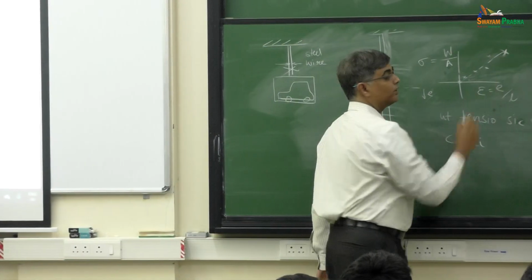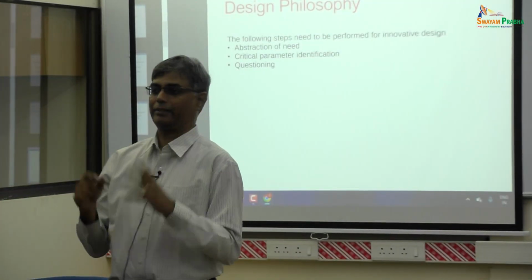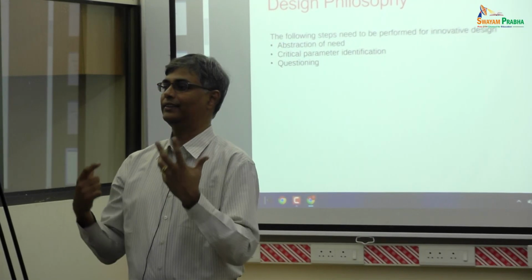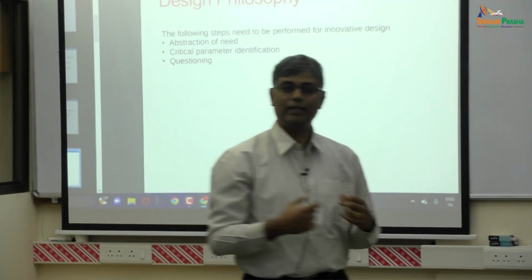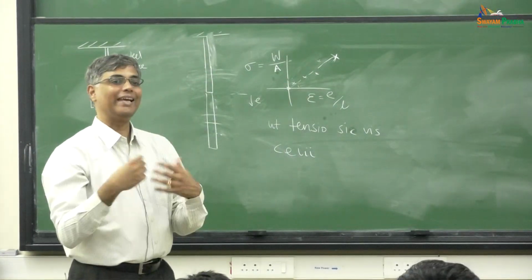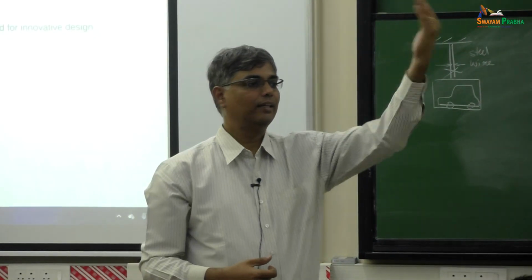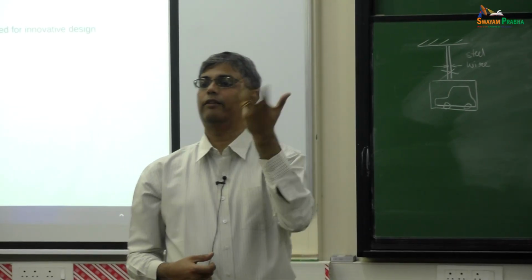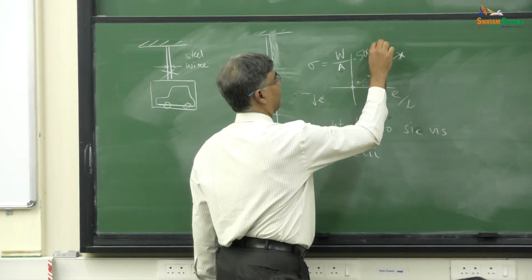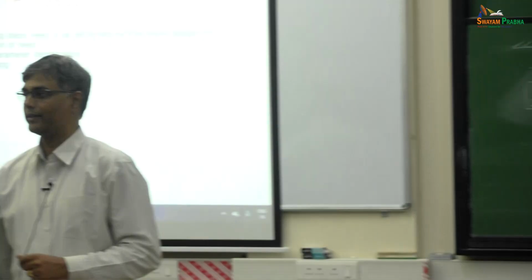We need to find out what is this failure point, at what point will something break. That also comes from experiments. For a given material, there will be some stress at which this material will fail. You should get a feel for some materials. Typically, mild steel, which is the very common material that we use. There are high strength steels, soft steels and so on. Mild steels will have a typical failure strength of about 500 megapascals. I hope you know pascals, so megapascals, 10 to the 6.